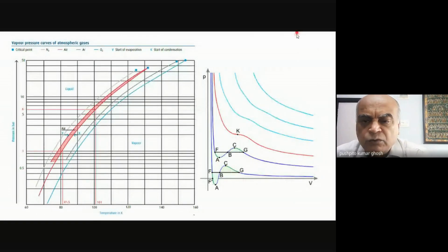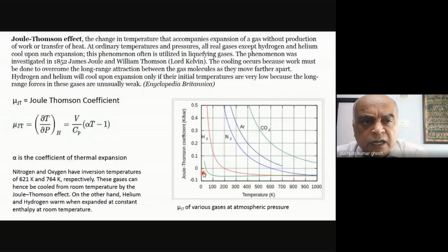It's all very easy to say as you lower the temperature. The question is, how do you lower the temperature to this point? It has to be lowered, right? And to something like minus 200 degrees Celsius temperature for nitrogen. So that's a very, very low temperature. And that's where really the Joule-Thomson effect comes in very handy, and the entire liquefaction process is really based on the Joule-Thomson effect. Is anyone familiar with the Joule-Thomson effect?